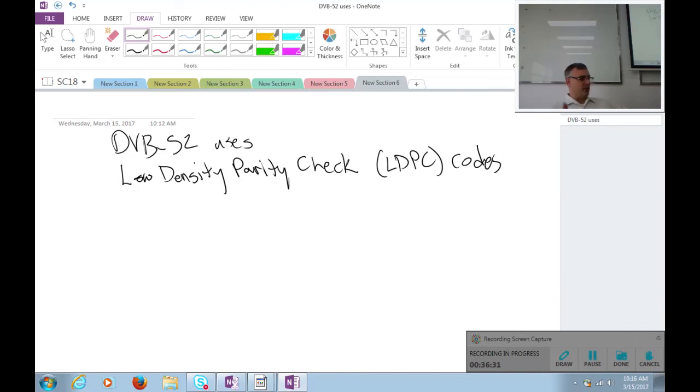and they published a great paper in 1996 on a method of coding called turbo coding, which was basically 2 different convolutional encoders that were interleaved and scrambled together, which you could iteratively decode and pull out the original signal. And voila, wouldn't you know it, we were within about a dB of the Shannon channel capacity using turbo codes. Well, that was really, really big and popular.